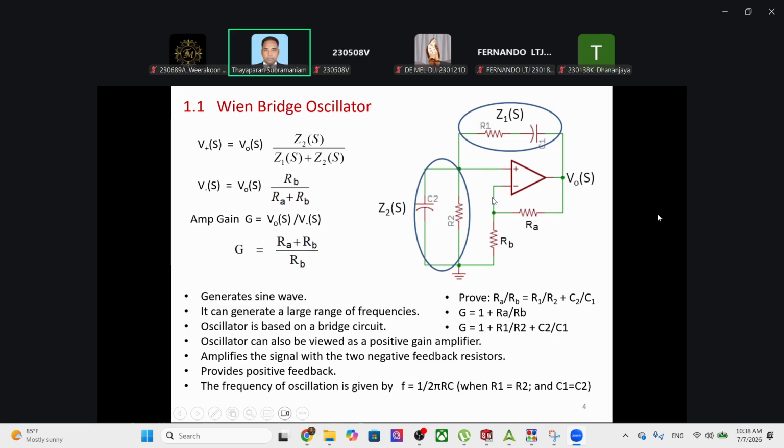So if that is 1 microamp, 2 microamp, then we have to make sure that the current through this path is at least 100 times that, so the input current has to be less than 1%, because RA and RB act like a potential divider here. Agree? That is what our equation says, V minus is equal to V out times RB divided by RA.